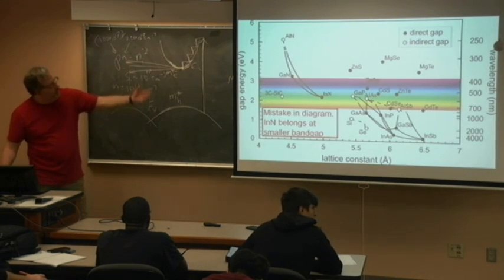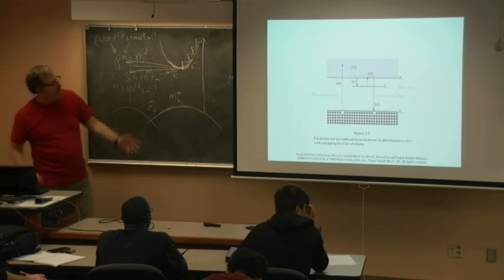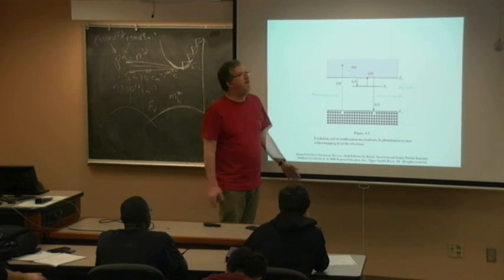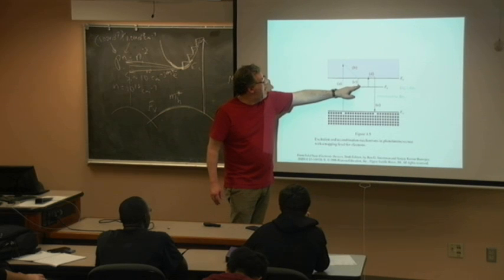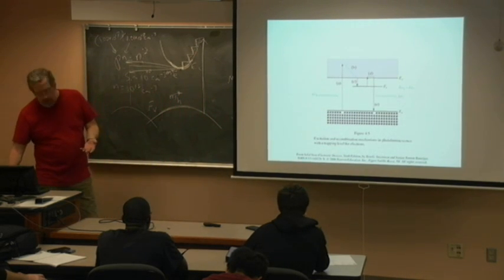Yeah, so here you can see the wavelengths expressed. And if you have a trap, a defect, one of those Frenkel defects, substitutional defects, vacancy defects that might create an energy level in the forbidden band gap, that can also be in play now if you have a poor quality crystal.